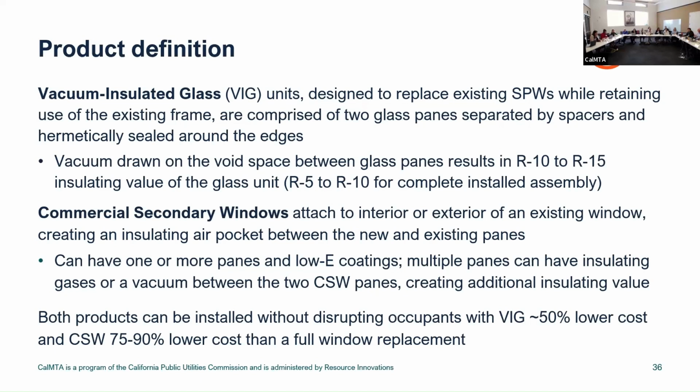So it makes use of the existing frame. We're not ripping out plaster, we're not removing bricks. It's a relatively elegant solution. What happens from an energy perspective is you can get very high performance with this, R10 to R15 from the glass itself, but you do get thermal transfer from the frame, so the overall system impact is going to be a little bit lower, R5 to R10. So just wanted to mention that.